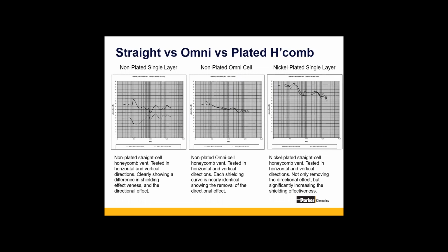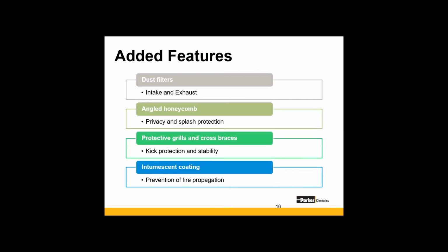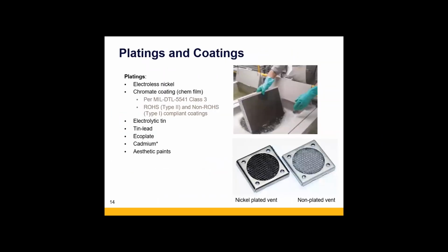And then from Sean, you may have missed it, but what is the thickness of the nickel? And is it electroless? So, Kevin, you want to take that one? Sure. So it depends on the type of application. To back up a little bit, the e-nickel plating is AMS 2404. That's the common industry spec.